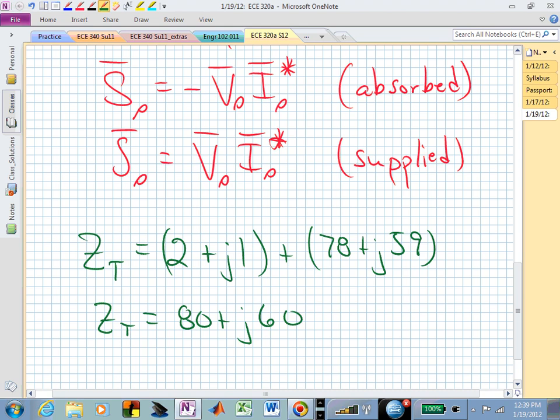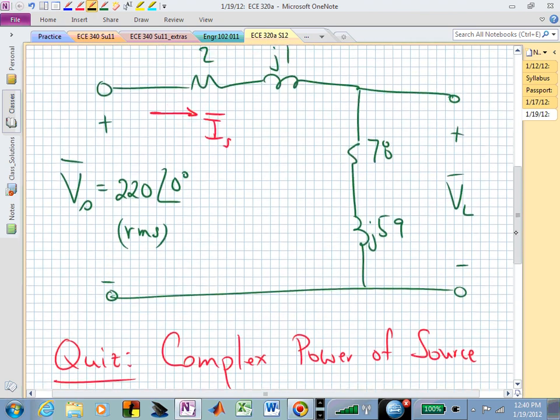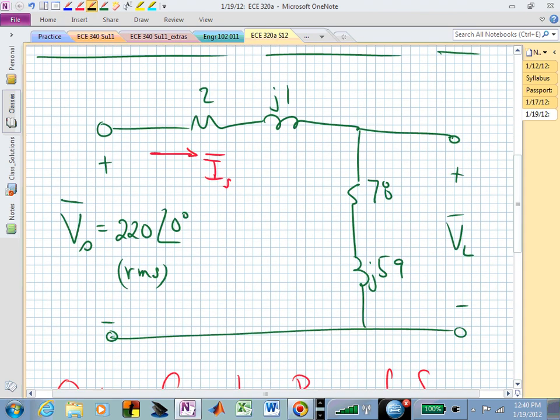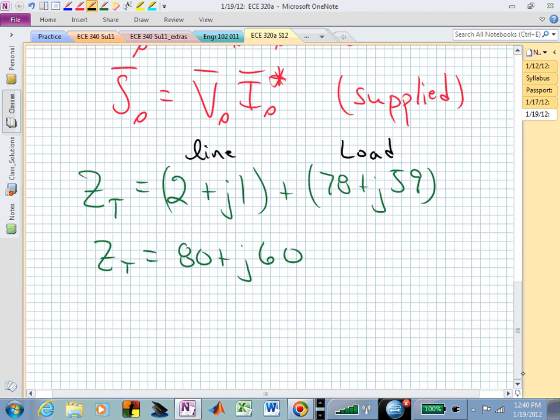So this was the line piece, and this was the load impedance. I've combined those. Those were just connected in series. I can combine those easily enough. And now to find the current, which is in series, it goes through all of those elements. The same current does. I sub s bar as a phasor will be V sub s over Z sub t.